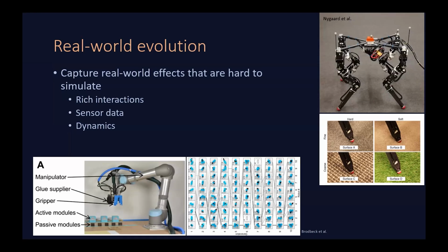But the disadvantage of this is that it takes a really long time, and unless your robot platform is very robust, there is some wear and tear of the robot, and properties of the robot system may change over time. It may heat up, for example, and you get different properties. So your evolution is maybe not so stable anymore. You need to consider that when you're evolving.